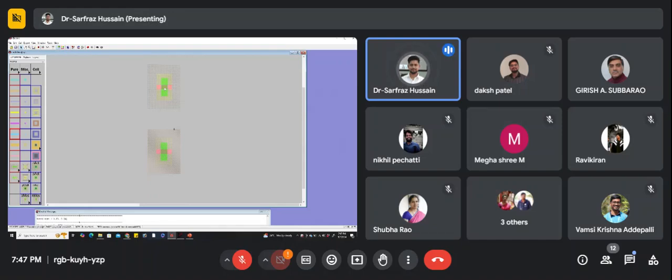First select this particular PMOS. After that, press Control I, and here we can make a rotation of, let's say, 90 degrees. Here you can see this. Similarly, you can do it for the NMOS also: press Control I and rotate it to 90 degrees.